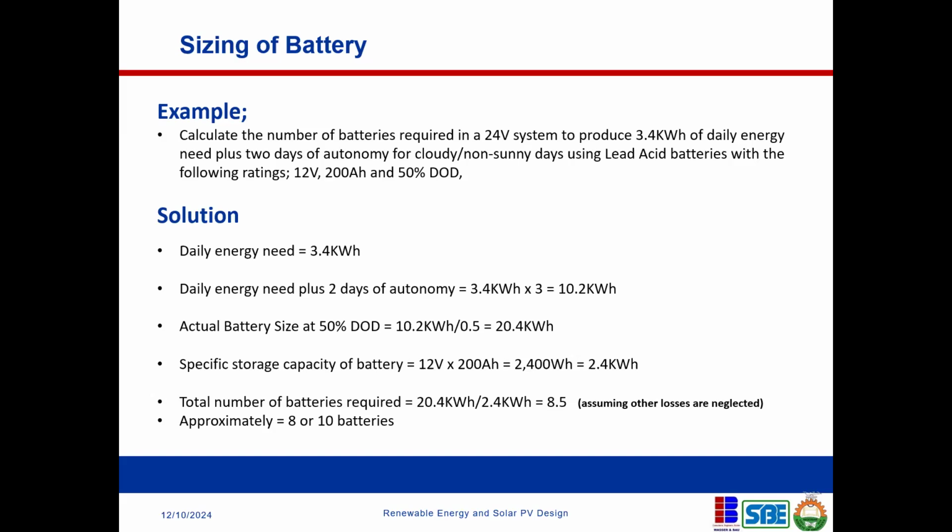I have one more question, please. With the current discussion, we're looking at a 24-volt system. So we're looking at 8 to 10 batteries. Automatically, using 12-volt batteries, we have to put them in parallel. What's the conclusion? If you're using 8 batteries, then you have to put 2 in series to get 24 volts, and then you do 4 pairs in parallel, 2 in series.